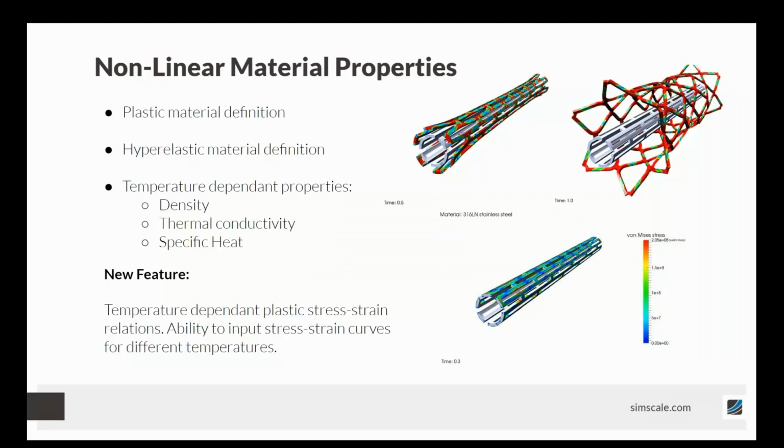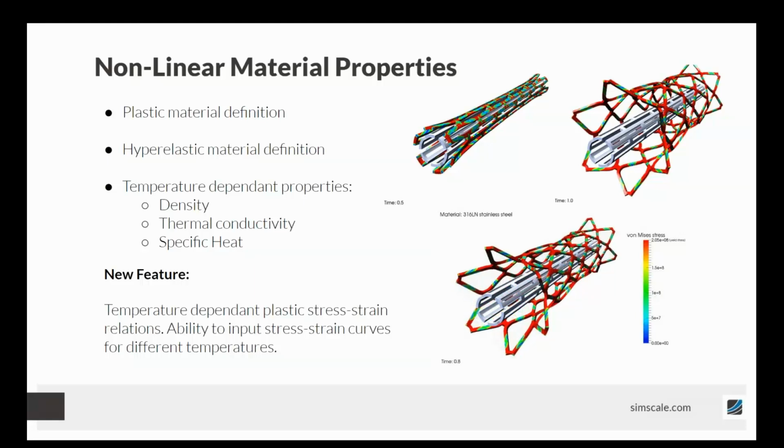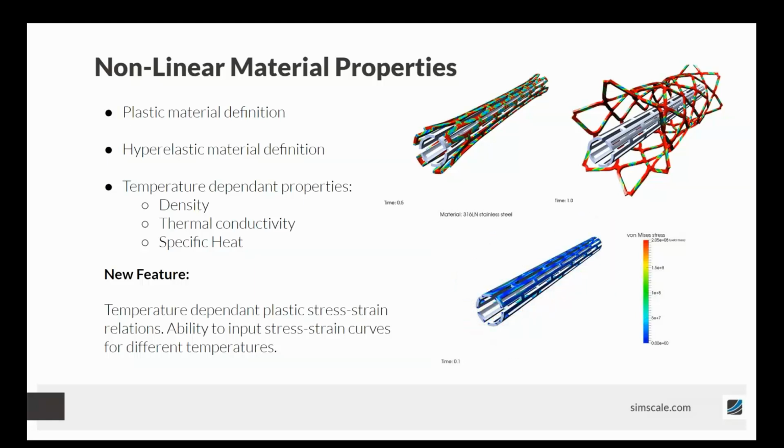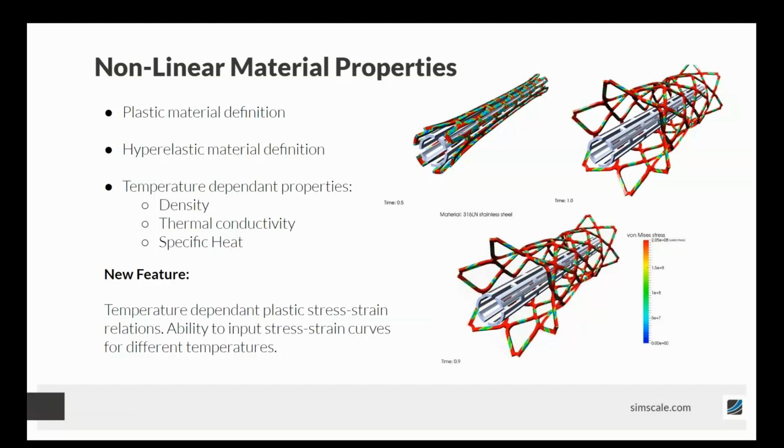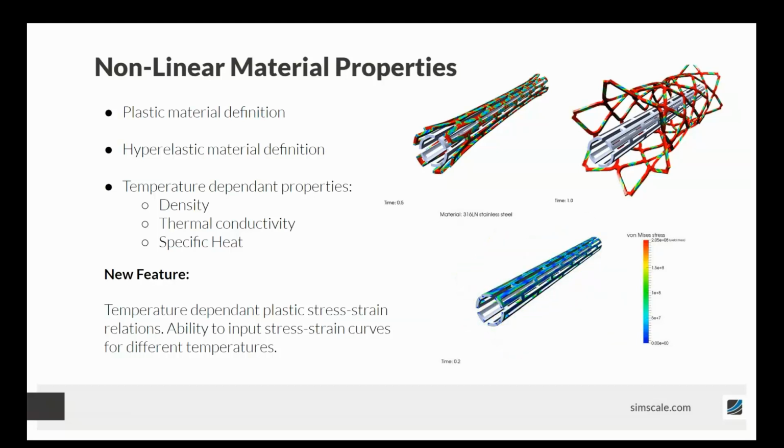Now today's topic, we are specifically looking at material nonlinearity, the first that I mentioned from the three nonlinearities that we cover. So what are the material nonlinearity phenomena that we're talking about? You could have materials that behave plastically above a certain strain. Then they plastically deform, meaning that deformation is actually going to remain deformation. It's not going to spring back like it would in the linear elastic region. So when we get into that plastic region, the properties of the material have physically changed.